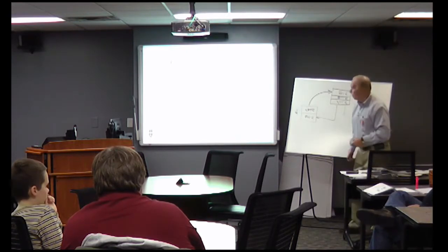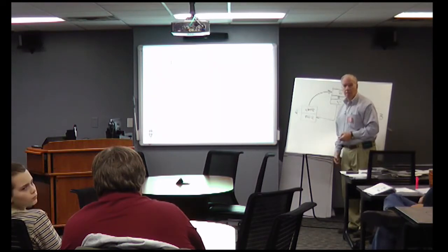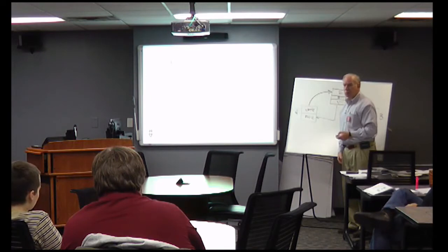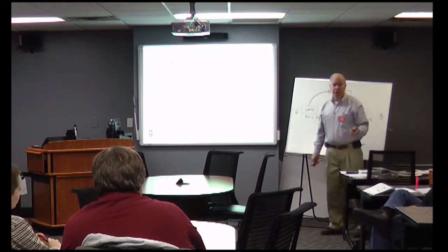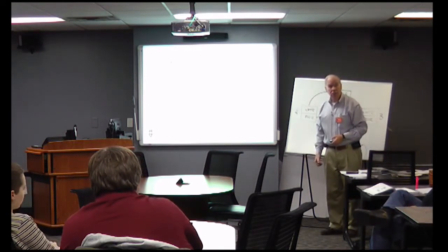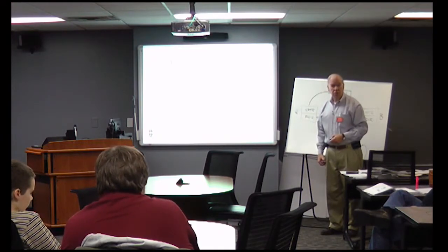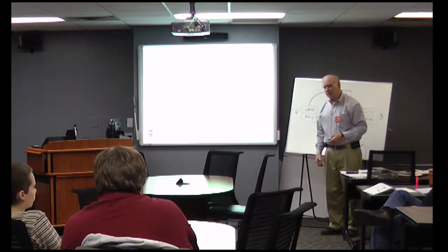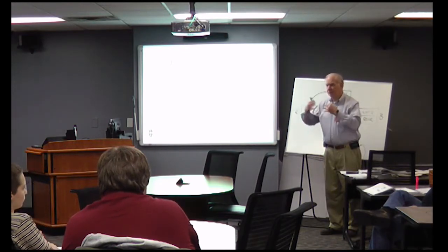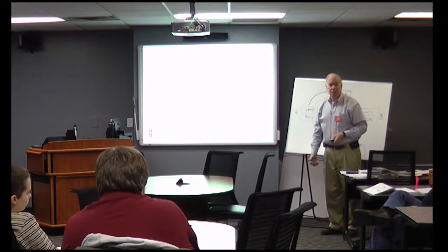Yes, sir. Can you help me define what you meant by a low power radio? What's low power? I mean, 5 watts, 10 watts? Well, if you're talking about a handheld radio, you're talking about maybe half a watt. Okay. Some up to 5 watts. So is there a range that would define a truly low power radio? Is it 10 watts and less? Not really. It depends on the geographical distance of the communications.